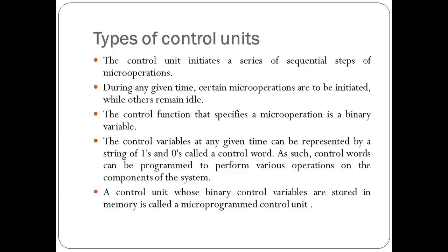Okay, if I write it in the form of a set of micro operations, which will be stored in a particular memory, we call it a control memory. So whenever a multiplication instruction is called, that particular program will be executed. That function is defined by the designer, not by the application user. This is the best example for a microprogrammed control unit.